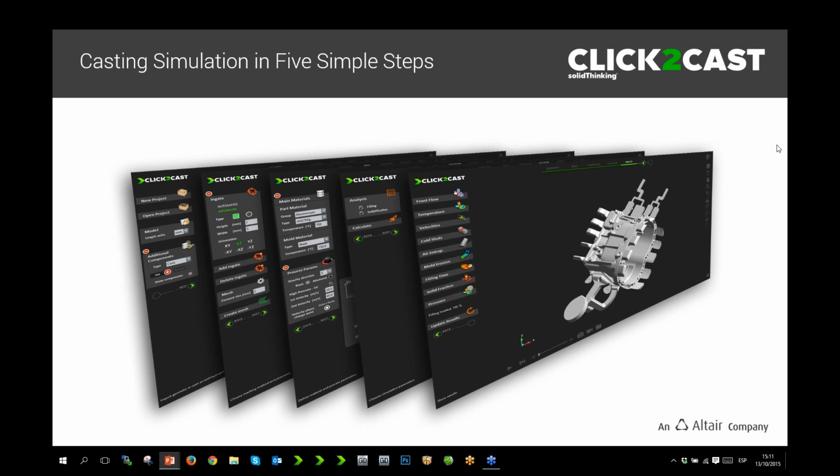But Click2Cast goes some steps before answering this question, and it helps us to determine the best position to place the ingate, or where to place feeders or risers, and which size we must allocate for these risers and feeders. It allows us to answer the question if we have to use continuous ingate or fan ingate, where to put vents or overflows, and how to balance the multi-cavity flow. All these questions are really easy to answer by using Click2Cast, starting from the raw part.